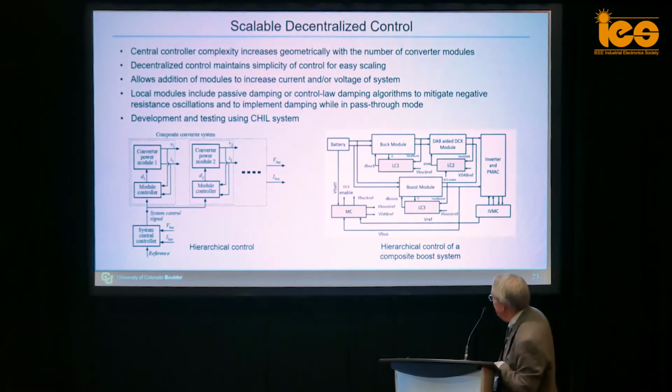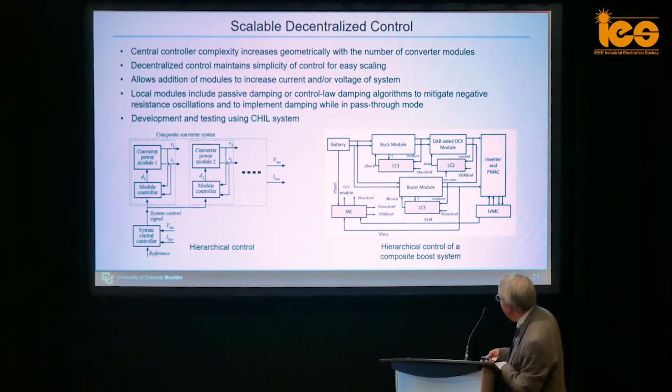We're currently working on decentralized control, so we have local controllers of each module to try to make it easier to control and easier to expand the system to more modules without having to start over and redesign a central controller. And there are issues like passive damping of converters in pass-through mode and negative resistance oscillations.